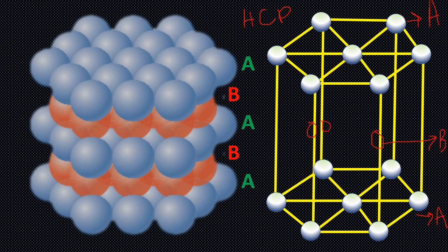It has the most efficient atomic packing factor, as we have already calculated for this structure, and it is equal to 0.75, the most efficient atomic packing factor for metallic crystal structures.